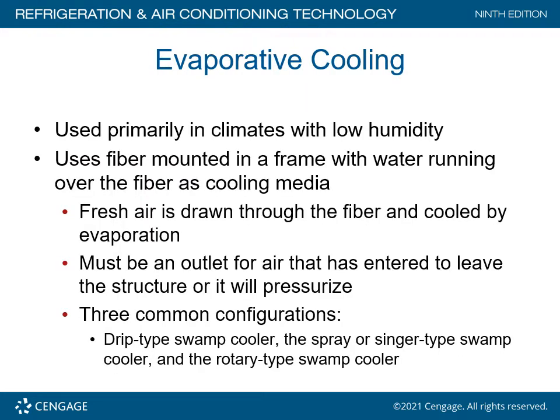Evaporative cooling. I've talked a lot about this in the past and I'll talk about it again. It is used primarily in climates with low humidity. SoCal coastal regions are not low-humidity areas. Typically our humidity here, between the ocean and I would say all the way to Riverside and San Bernardino, is typically 40% relative humidity. Well, Larry, it feels hot and dry. Yes, during Santa Ana wind events, it does.